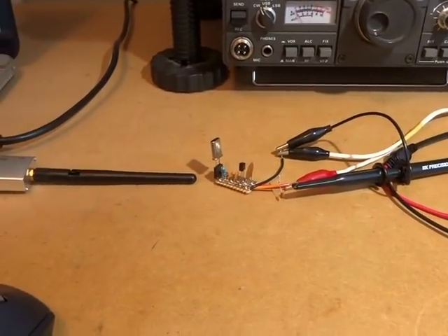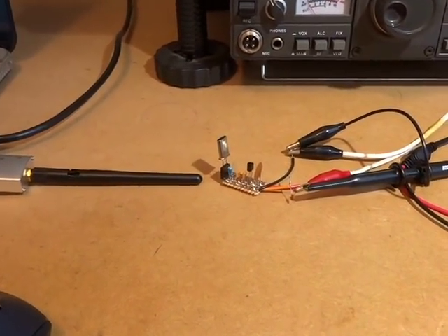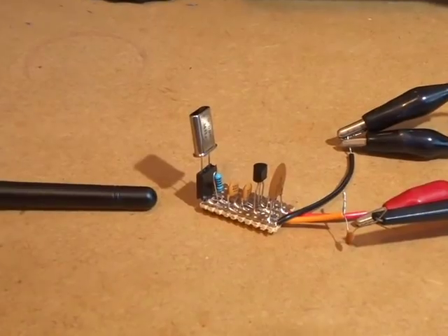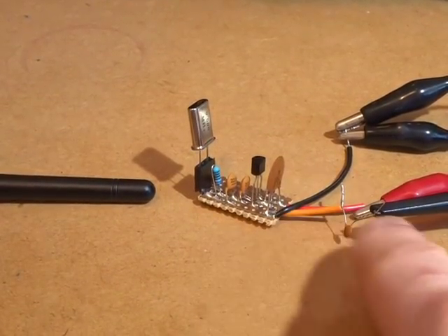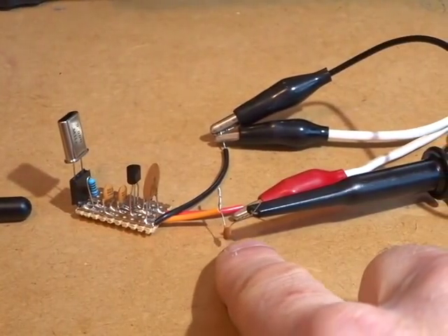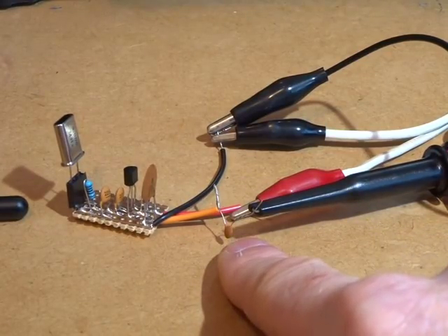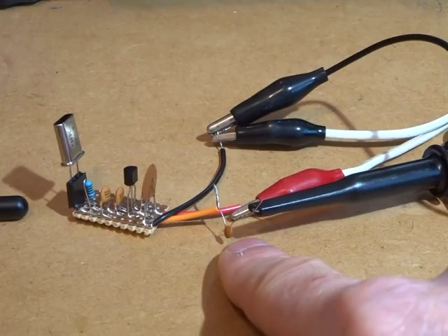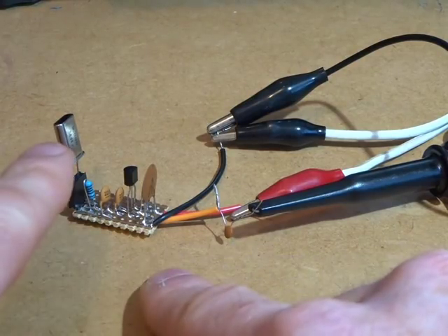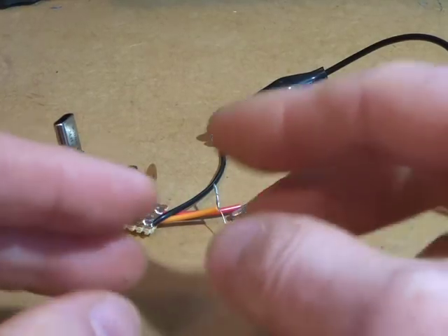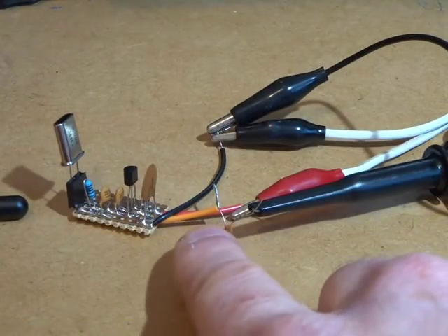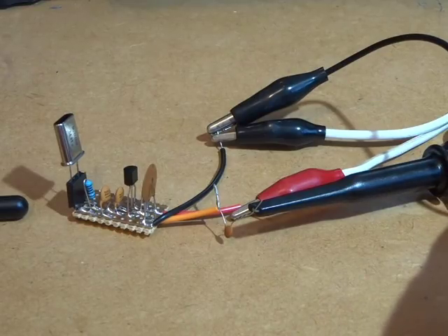I have down here a crystal that's sitting in that crystal oscillator. I'm taking its output and I'm loosely coupling it to my oscilloscope input using a 10 picofarad capacitor. So again, this is stage 2 now, so we've been through the SDR program and we've got a number of crystals which appear to be close to each other. So I'm loosely coupling that through the oscilloscope.